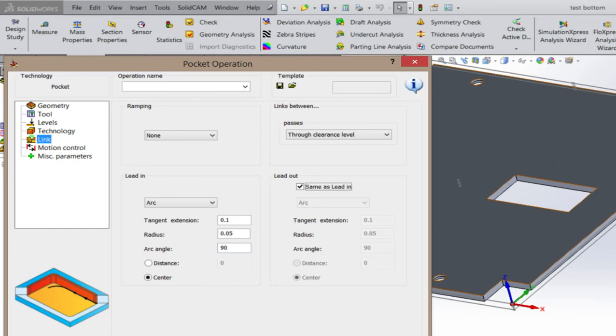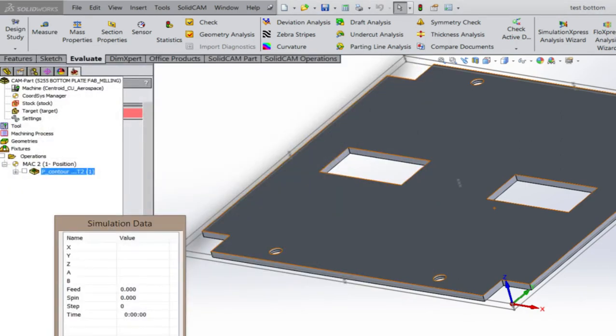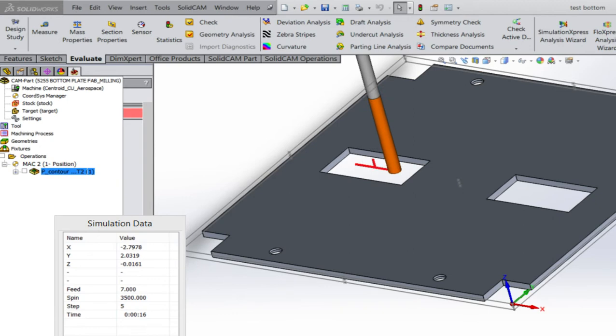All right, let's save and calculate that. And then let's verify that guy. So we'll simulate it. So we'll step. Again, now it's at 16. That changed because I added a delta, so it recalculated its depth cuts. So it's at 16, then it goes to 32.